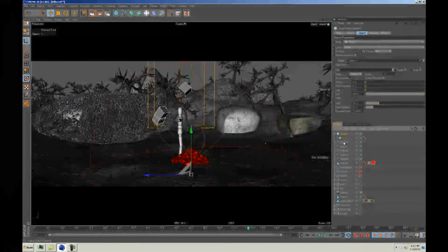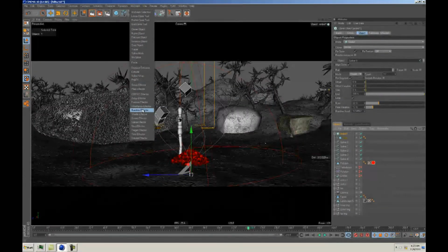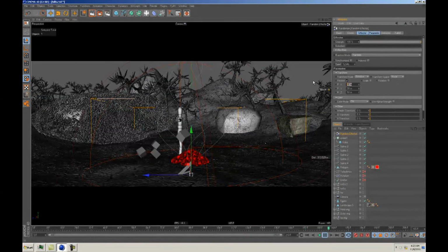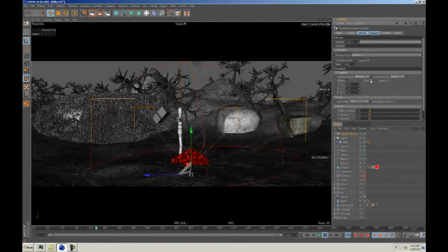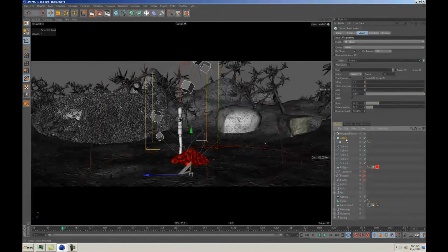And then all we have to do is go and make a bunch of those cloners. But before we do that, how about we add some randomness to them, just because it helps so much. Not that much random. Just a little bit. Like that, and like that. I'm telling you, these random effectors are magical. And unlike the other one, I think we could change the scale in the regular particle effector too. Let's change some rotation, although it randomizes the rotation. So now we have it looking a little more organic, and that's what we want.